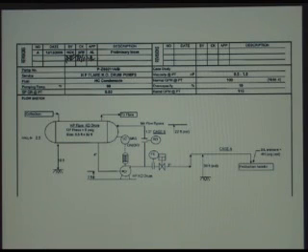Off of the discharge, you see a flow element and then a control valve, probably to control the flow because that's part of the process requirements. It shows the high static elevation that the piping is supposed to go to. And this is an interesting feature. It has a minimum flow bypass with a restriction orifice, so it's continually bypassing a certain amount of fluid back to the reservoir to protect the pump. We'll get into pump protection a little bit.